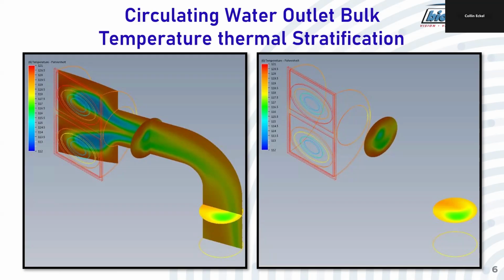So the information obtained from the thermal maps is used in conjunction with computational fluid dynamics software to properly locate a suitable location for a single measurement point or an array of measurements. By modeling the outlet water box and piping, and using flow rate and these temperature profiles, you can visualize and quantify the temperature as it mixes and travels down the circulating water pipe. For this particular installation, the pipe went underground, right where you see it end here on the model. So there was no other downstream location accessible. So we were forced to find locations in here to install our temperature measurements.